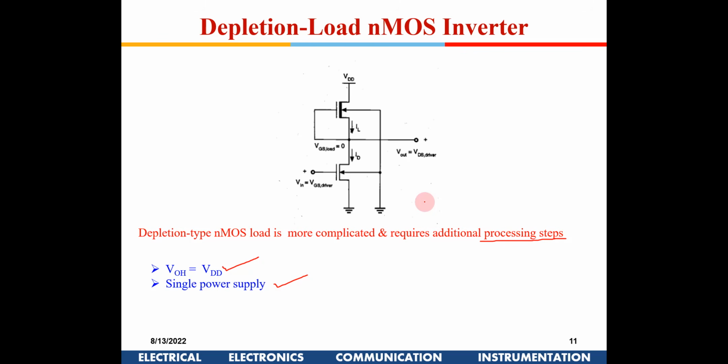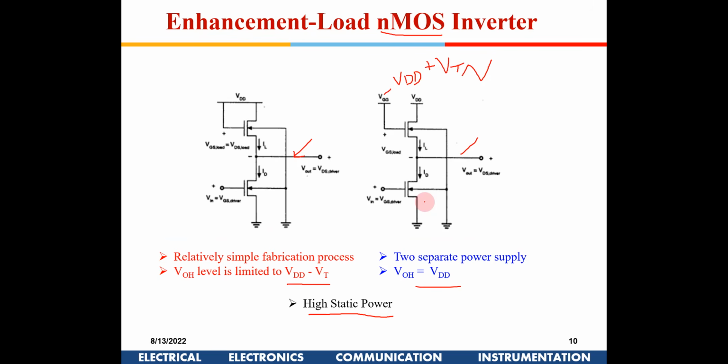Sir, in the previous slide, one more back. Yeah. Here I didn't get why VDD minus VT is there for the VOH level. Yeah, we talked about when we have an nMOS, it cannot transmit a perfect 1. Now if I take an example out here, when the output reaches VDD minus VTN, what would be the gate to source voltage now?